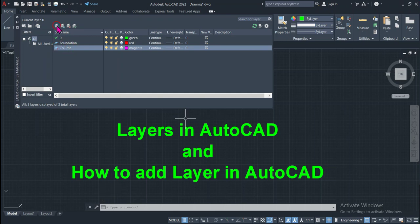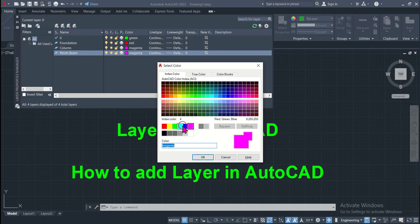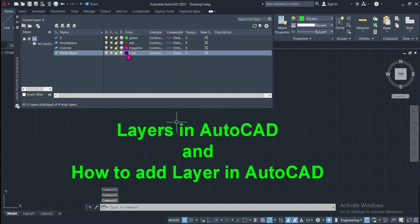If we want to add another, we click on this option and a layer will be generated. We want to name it plinth beam, and we want to assign it a blue color. So we click on OK. Blue color has been assigned to the layer which we named plinth beam.